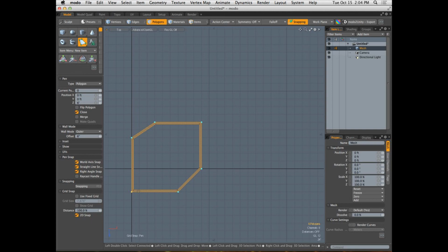All right. So actually, Brandon just kind of interfaced with something that can be a little bit of a nightmare. He had his grid snap on, and the computer was trying to snap to the grid points, but Brandon wasn't able to put his control vertice where he needed it in order to get the 90-degree angles on those walls. So that's why being able to turn your snapping engine on and off is invaluable.